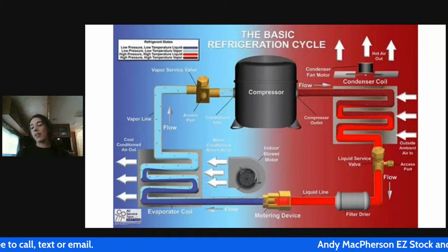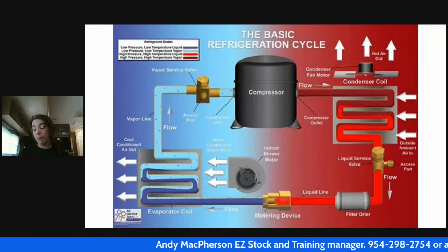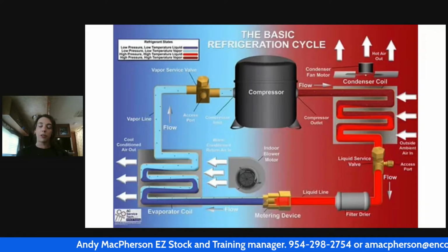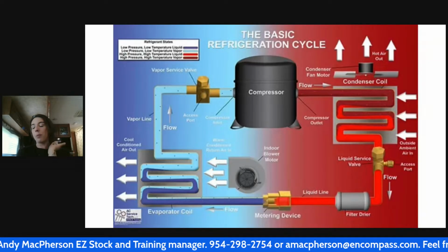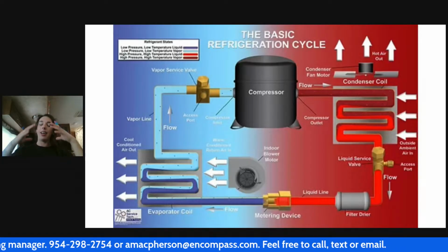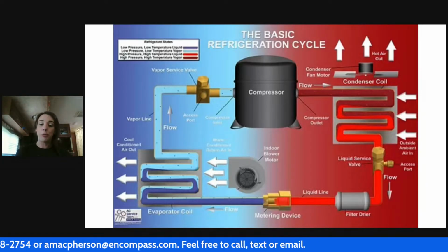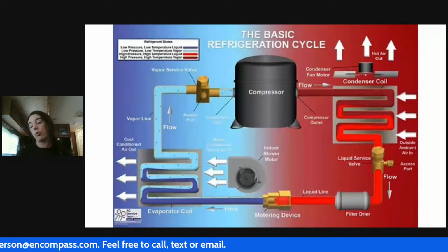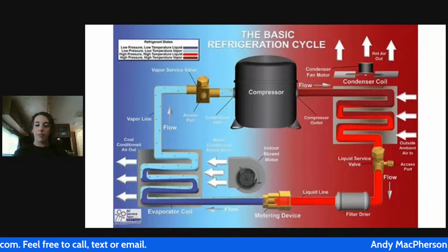Now we have the capability to go so much lower than that, and we really need to be pulling as deep a vacuum as possible. And if anybody's ever told you that if you pull too fast of a vacuum or too deep of a vacuum, that the water molecules will freeze within the system, it's possible under certain circumstances, but it's not widely possible. You do not need to worry about that. Pull as deep of a vacuum as you can.